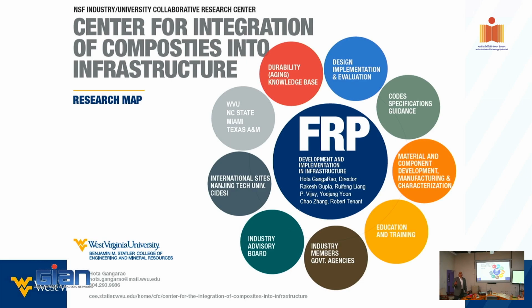So if you have a hand layup type process, obviously it's not going to be as consistent as a mechanized process. It will not be as high grade as a mechanized process. So those are some of the things I will be focusing briefly again on pultrusion as one of the manufacturing things. Compression molding is another. We call it VARTM, vacuum assisted resin transfer. So I'll again touch upon them.